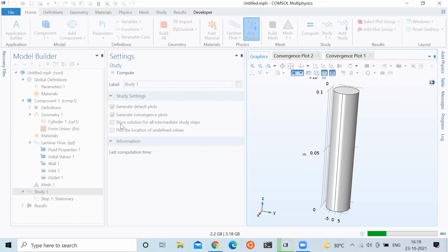So that is the good thing about COMSOL: when I have chosen physics-controlled mesh, it will automatically resolve the mesh at those places where it is needed. So you don't have to worry about them. As you just mentioned, at these corners of the walls, it will be resolved. I can show you the mesh once again after this is done.